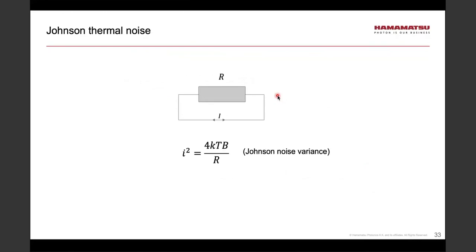Another source of noise is the resistor itself. Suppose I have a resistor here, which is not biased. Suppose I connect its two legs with a wire. Because of thermal fluctuations, you could have tiny currents flowing back and forth with a mean value equal to 0. However, the noise around that 0, the RMS value, will not be 0, and it's given by the equation below,